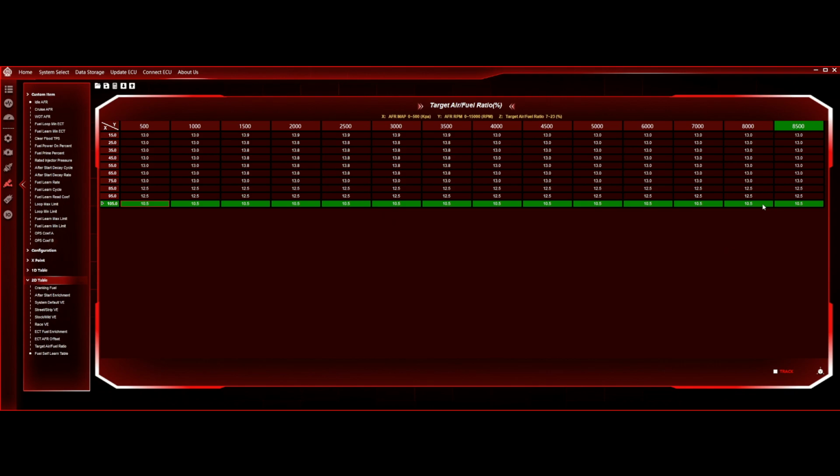It's not just for power, it's to keep your engine healthy. You're cooling the engine down while also producing power and lubricating it. So you have to be even richer than a typical piston engine. This might be extremely rich on a normal piston engine, but for a rotary, this is a pretty safe number as far as everything that I have read and watched for tuning rotaries.